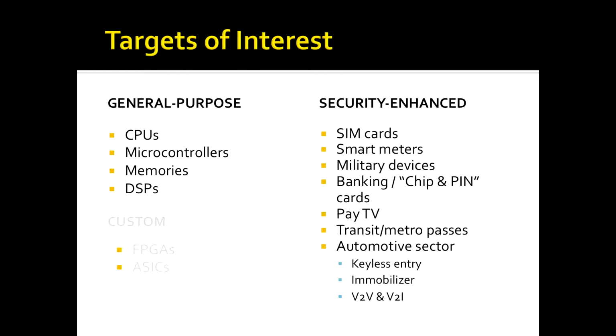However, on the security enhanced side, I'm not saying stuff's going to work necessarily there. It depends on the age of the device and how smart the developers were when they made it. A lot of these security enhanced devices are actually really, really good. So things I don't recommend is trying to attack FPGAs or ASICs simply because there's so many unknown variables, and unless you know there's a certain CPU core inside that ASIC or that they've programmed a certain block of logic in the FPGA, you'd be fishing around in the dark basically.